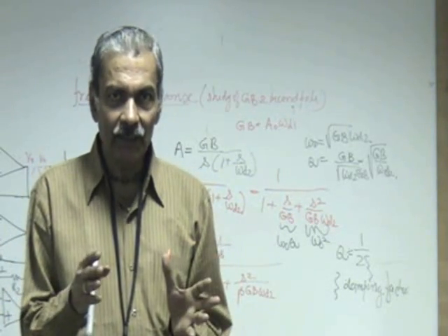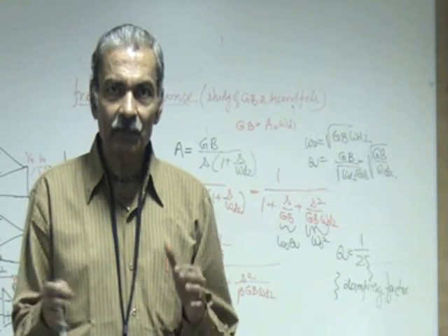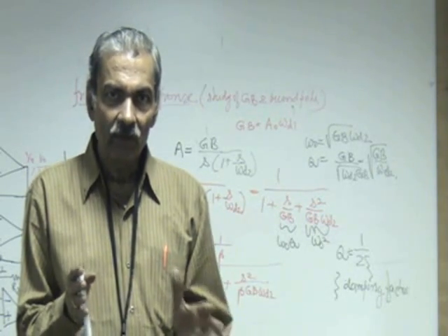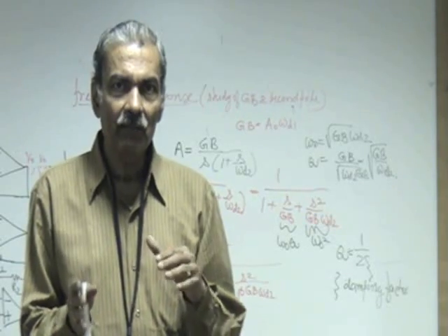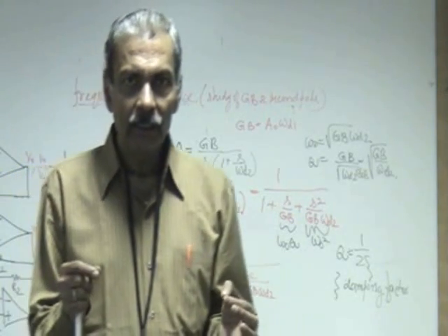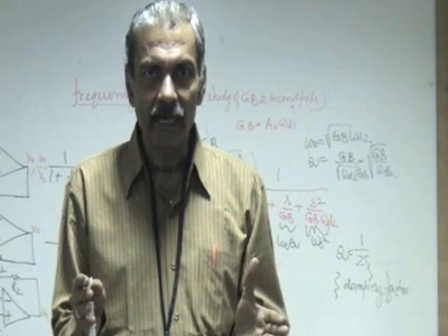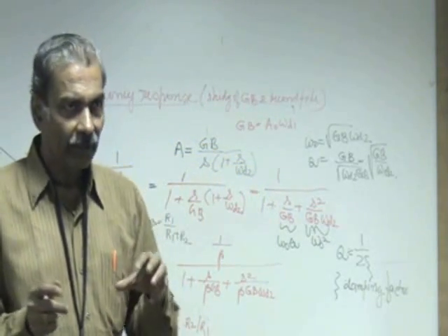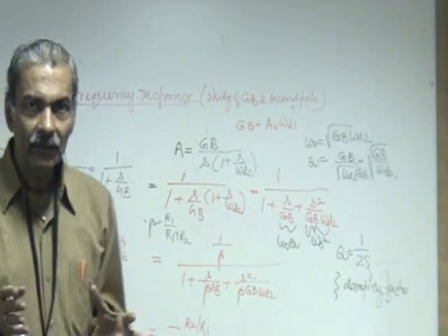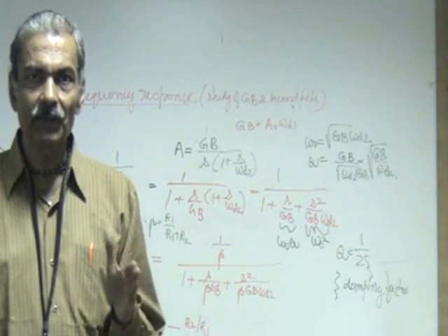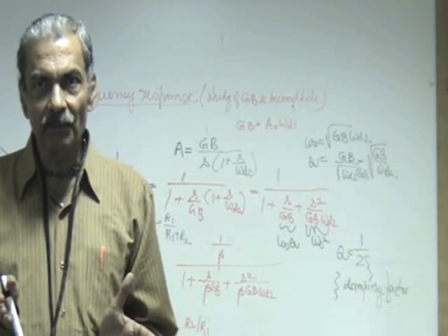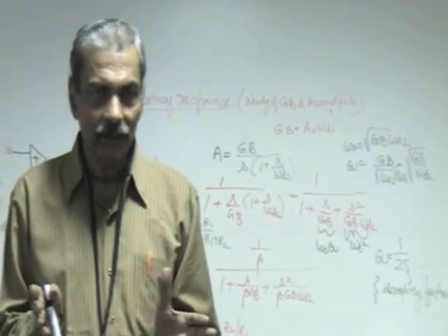And if the system is a first order system, then it will go on with exponential rate, and that again takes infinite amount of time for the system to come to steady state. We want an optimum result. So Q is normally made equal to 1, so that in the ringing there is just one peak, so that it quickly goes to the steady state and settles there. And therefore this is a design measure. So we try to locate the second pole in such a manner that the transient response of the system becomes good. This therefore will facilitate a measurement of omega D2 and the gain bandwidth product of the op-amp.